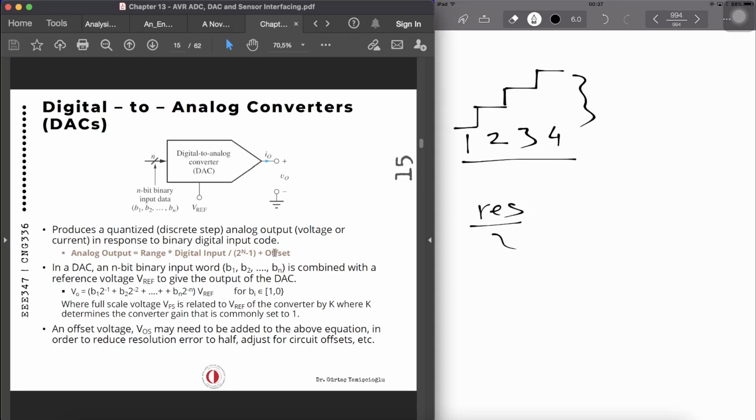So whenever we receive a particular bit setting, we get a kind of mid-range value. And this will make sure that whatever errors we have are plus or minus half a resolution instead of 0 and plus full resolution. So we are making the error symmetric around our outputs.